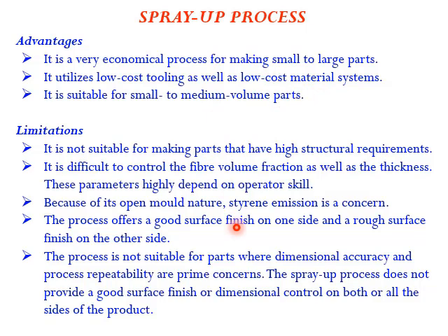Limitations: it is not suitable for making parts with a high structural requirement. It is difficult to control the fiber volume fraction as well as the thickness. These parameters are highly dependent on the operator skill. Because of its open mold process, styrene emission is a concern. Whenever we spray the resin material, it may get deposited on the outer world also, or it may be a health concern to the operator also.